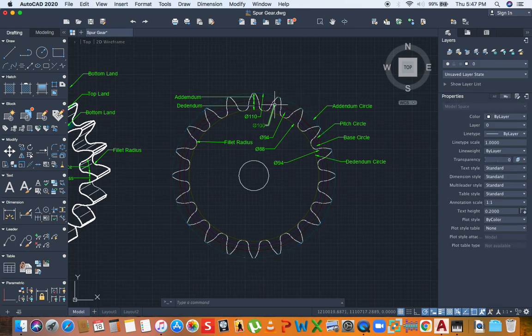All four circles are critical in constructing the gear tooth profile or the spur gear itself. Now, I've seen where various persons start off with various circles, but I like to start off with the pitch circle. I realize that most persons start off with the pitch circle, right? And for a very good reason. To me, it's easier that way.